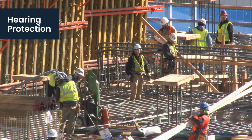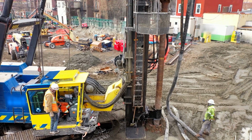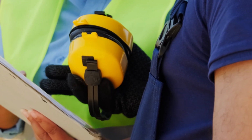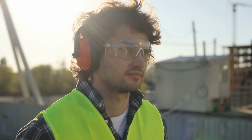Construction sites can be noisy, and constant exposure can lead to significant hearing loss. When noise levels get too high or last for too long, OSHA requires your employer to provide suitable hearing protection. This could be in-ear earplugs or over-the-ear earmuffs, but never plain cotton. It simply doesn't lower noise levels enough to keep your ears safe.